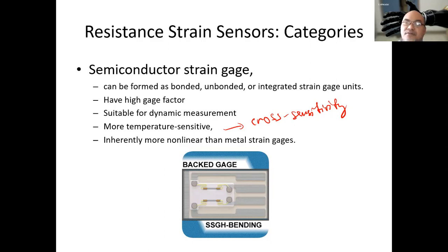The other sensor is attached on a surface of that structure which does not sense the strain, but only senses temperature change in the environment. Then you can subtract the response of the temperature-only strain gauge from the response of the strain gauge that measures both strain and temperature. This is one way, not the only way, to solve the cross sensitivity problem.